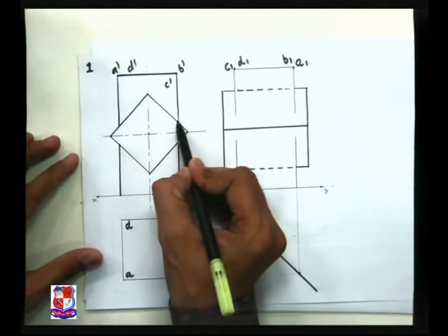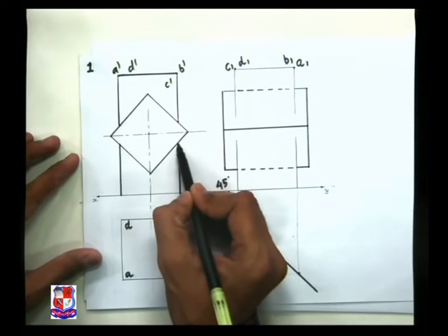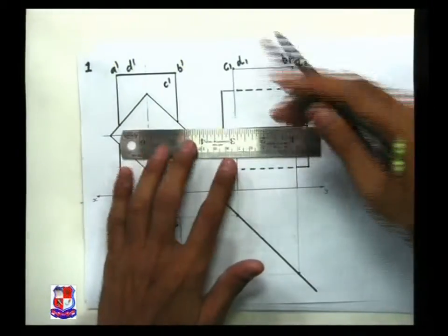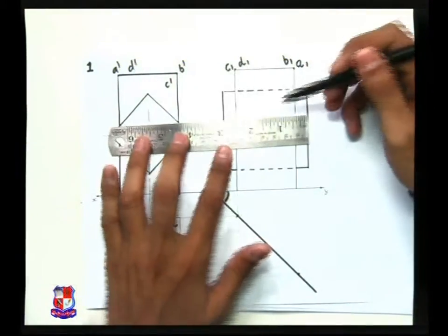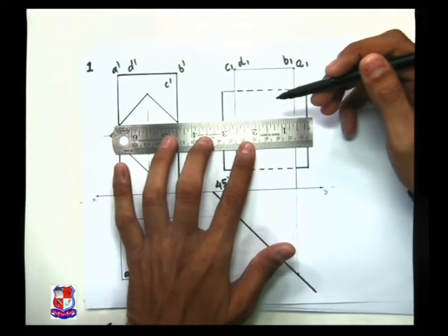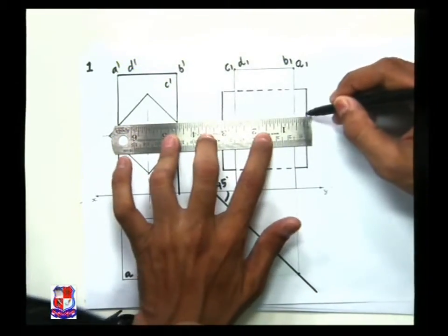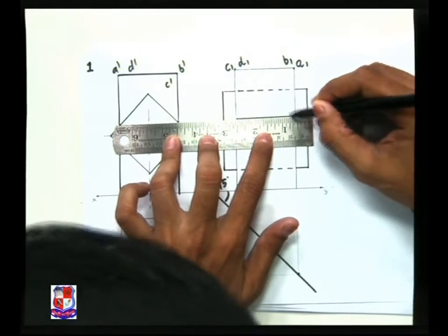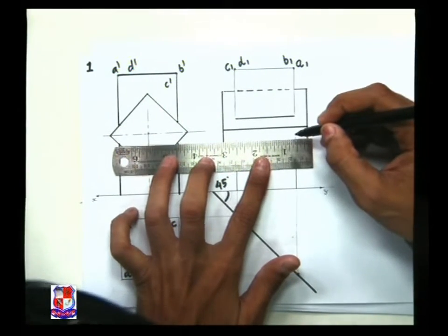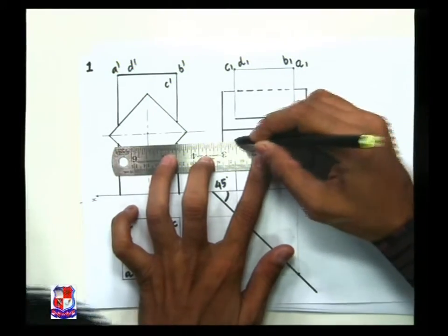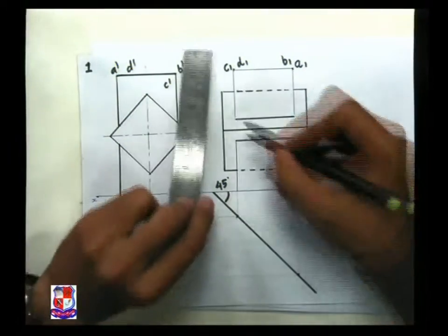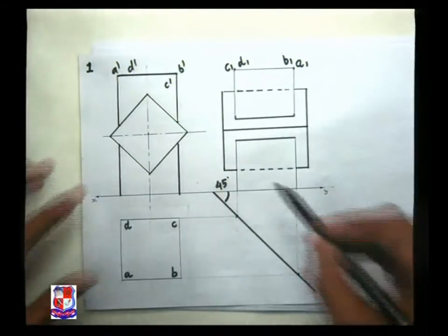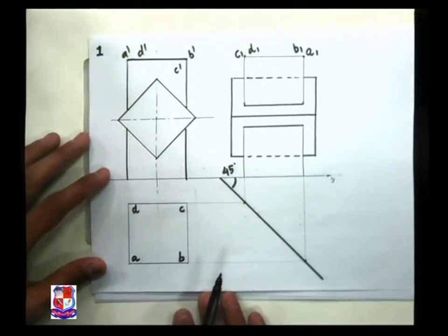Now we think about this point. These are the points 1, 2, 3 and 4, the points of intersection. So from all these 4 points, let me take projections. For that, from these 2 points draw a straight horizontal line, and this horizontal line will pass through the same points, and it will appear like this from this end to this end only. Full line would be there. Similarly here also full line would be there. So this we have drawn, and this height would coincide with this. After that lines will not be there. So this is the front view, side view of the given assembly.